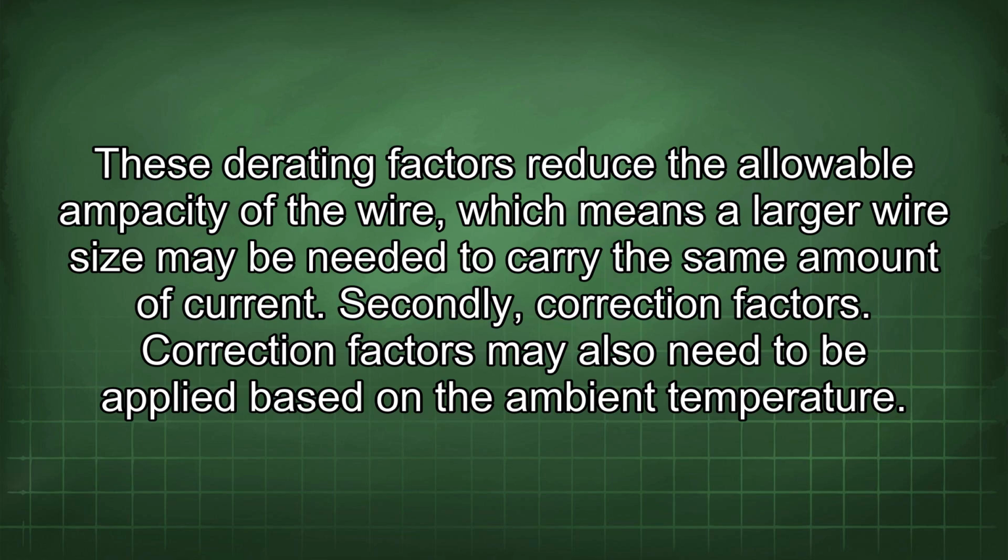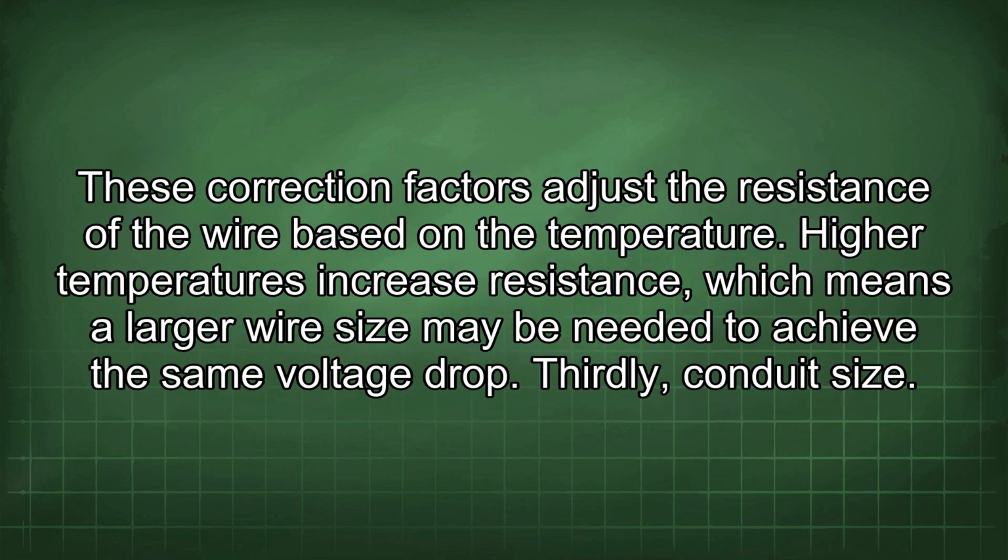Secondly, correction factors. Correction factors may also need to be applied based on the ambient temperature. These correction factors adjust the resistance of the wire based on the temperature. Higher temperatures increase resistance, which means a larger wire size may be needed to achieve the same voltage drop.